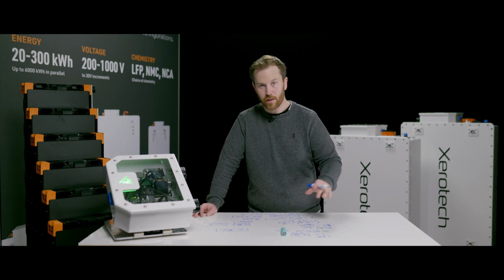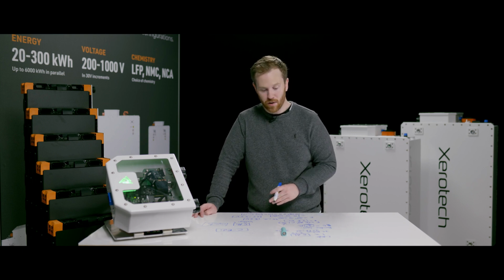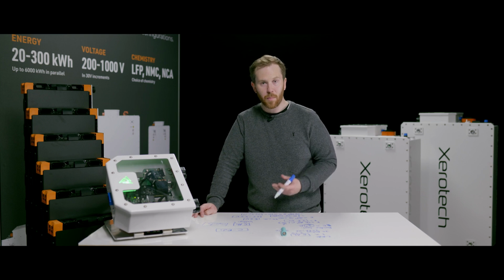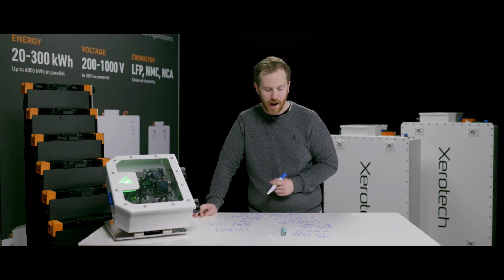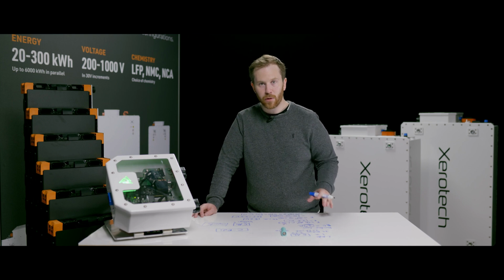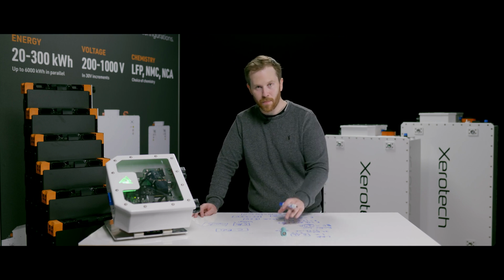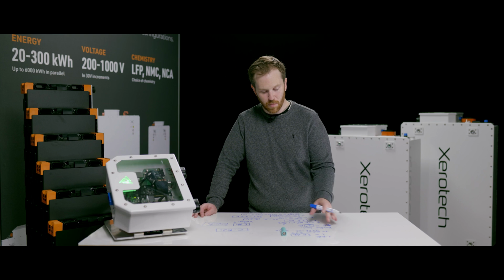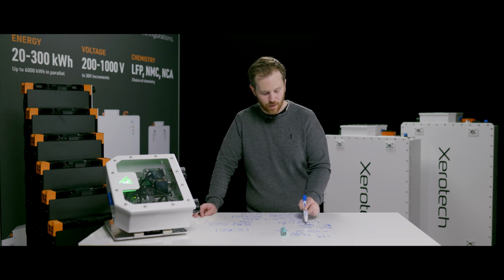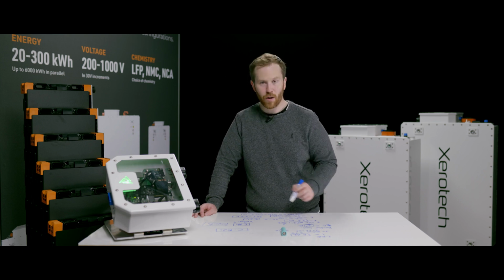So keeping the currents low is very important within a battery to make sure it lasts a long time. But similarly, when you design a battery pack, you want to make sure that the voltage of the battery pack can be a lot higher, so all of your conductors in the battery are not generating lots of heat because of this square of current.